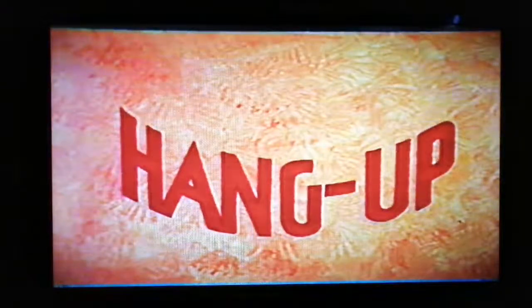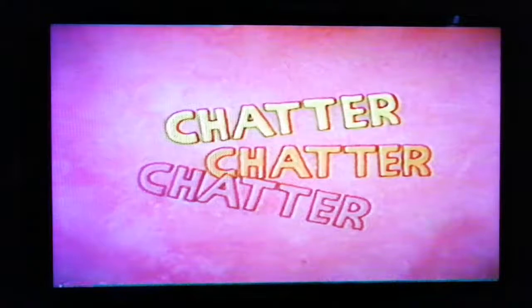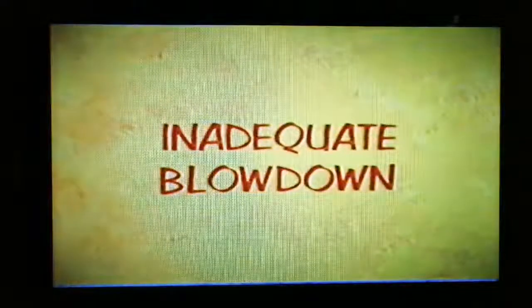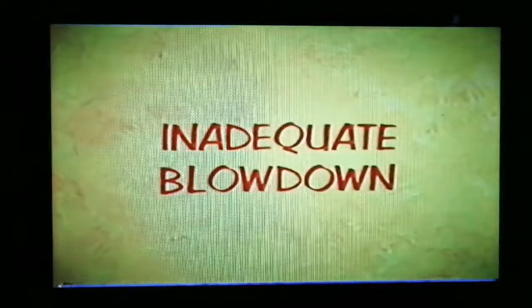Chattering is usually a metallic hammering sound, and this can take place immediately after popping or just before closing. If chattering takes place immediately after popping, it indicates insufficient steam or excessive back pressure. If chatter takes place just before closing, it indicates inadequate blowdown, which means the adjusting ring is out of position. In either case, chatter must be stopped quickly, or the valve seat will be ruined.